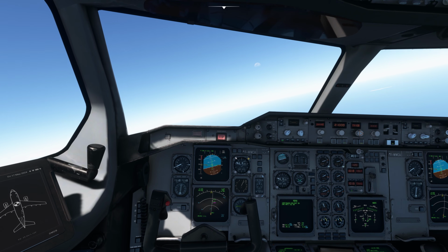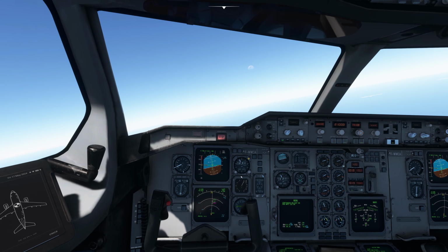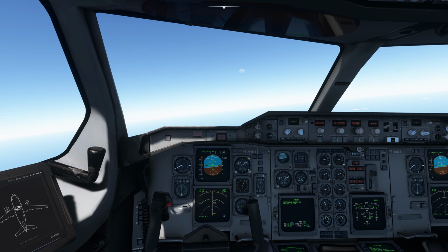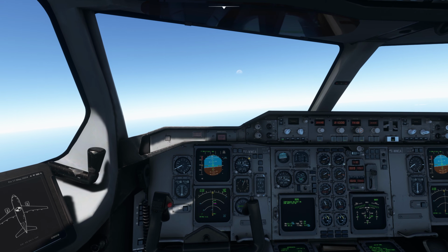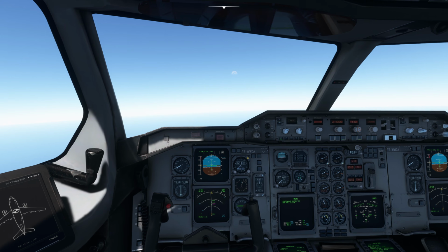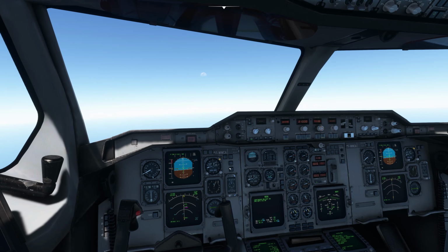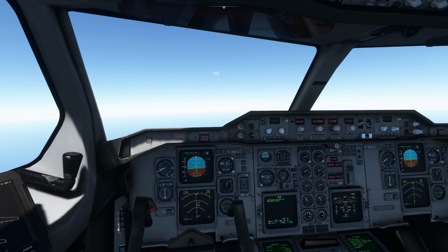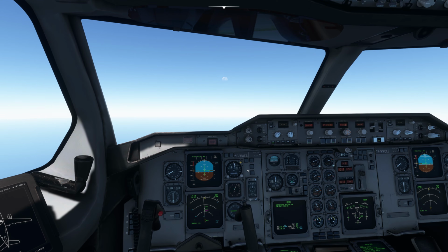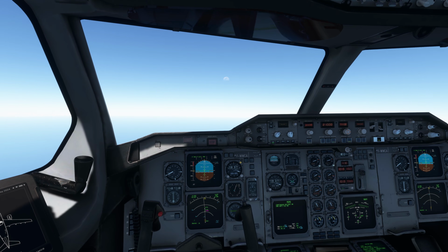And as the plane has now crossed the flight level of 13,000 feet, which is the transition altitude, I can bring the cursor over here. As soon as I see the up arrow, I will press this button. Down arrow. Once you see the down arrow, you press this button and you see standard. Now you can see the altitude is now set across the three instruments, because I've set the settings over here in the electronic flight bag according to that. So that's why standard is coming on all the three altimeters. And during the descent, whatever the transition level is for the airport, I will again change the standard barometric pressure to the given one.